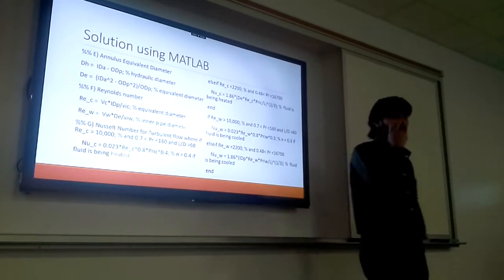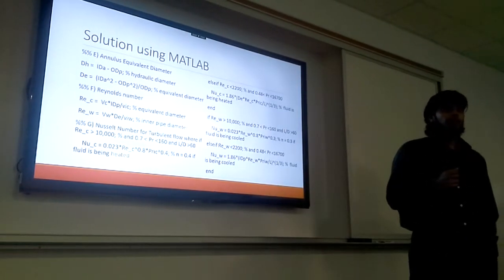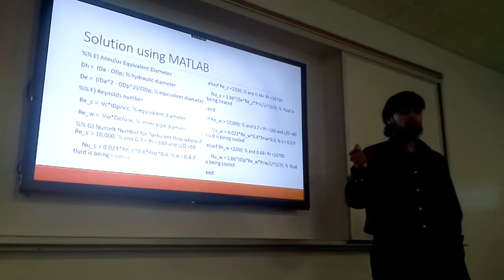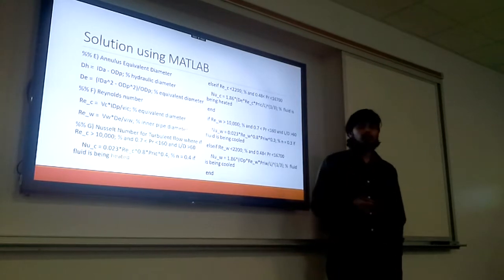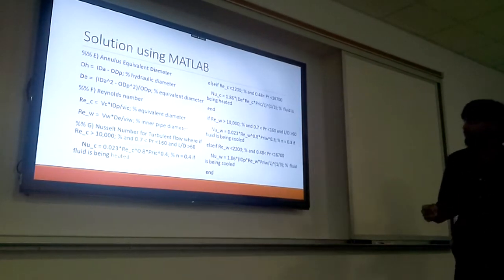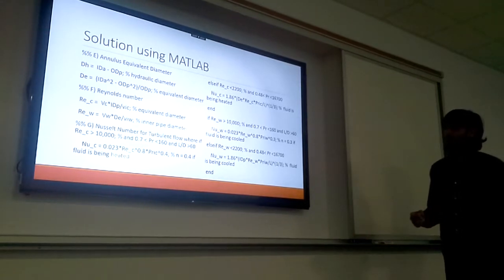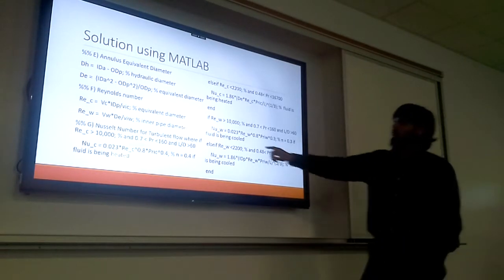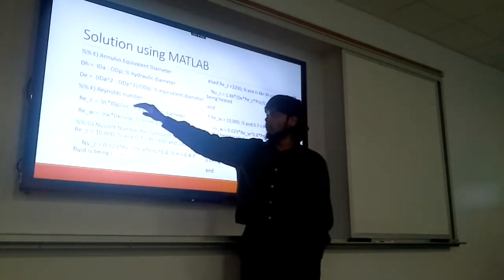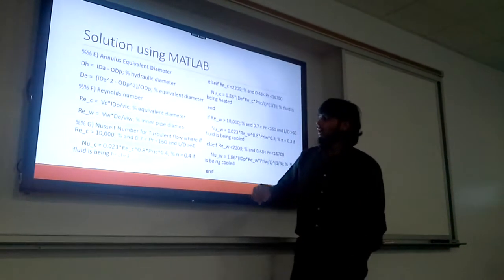give you what? What can the Nusselt number give you? The Nusselt number gives you what coefficient? Convection. Convection coefficient, exactly. Or any heat transfer coefficient that we need here. So that's where you find the Reynolds number for both the cold and the warm fluid, and the Nusselt number based